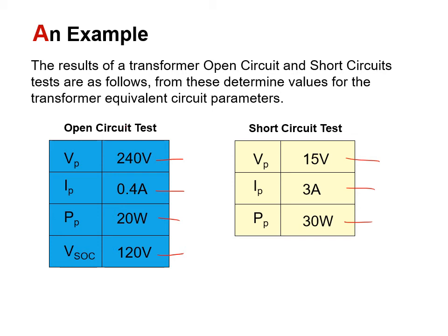And similar to the short circuit test, the current that's drawn is really dependent upon the values of those inductance and resistance values. So they're much smaller than you will have in practice. So the currents are quite small. It's one of the reasons why we like to do these tests.